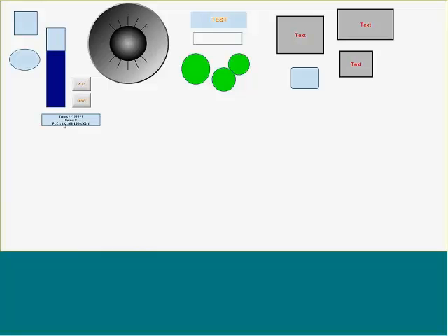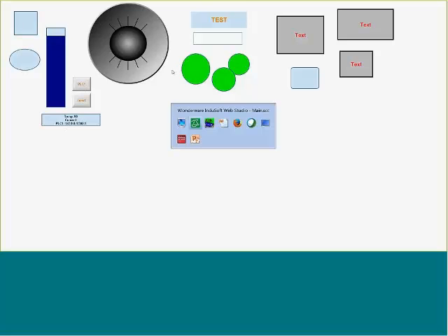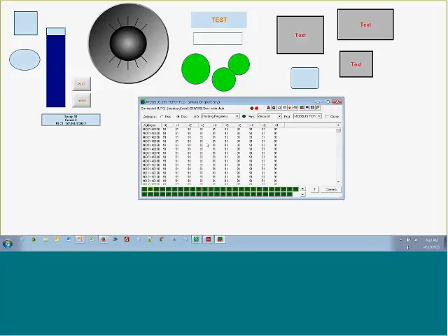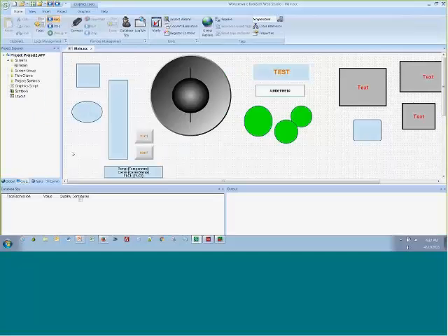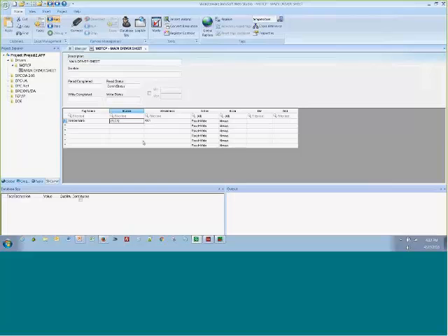So you can see that right now that PLC address is different, because I changed it with this button. Let me put it back. So it went to 127.0.0.1, and now I have good communications. And let's go ahead and change the value of that down to something, because it's going to go off the scale here in a minute. So that's a technique that you can use to change the PLC IP address during runtime. What's really convenient, especially if you have multiple PLCs.